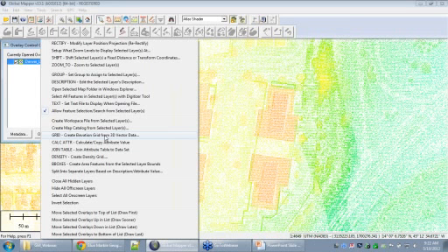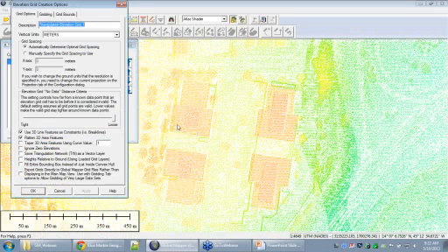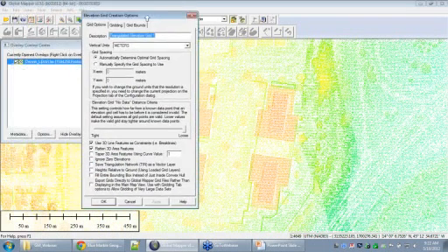This happens to be a LiDAR file, which is just one type of the many types of vector data we support in here. We can do this starting off from contour layers or simply distributed points that you've collected around an area and create elevation grids from those as well. So I'll create that grid surface. What I'm going to do is allow the application to automatically determine the best spacing to create that grid. So essentially what we're going to be doing here is sampling all of those points and creating a triangulated network, sort of the standard way to create surfaces in there.